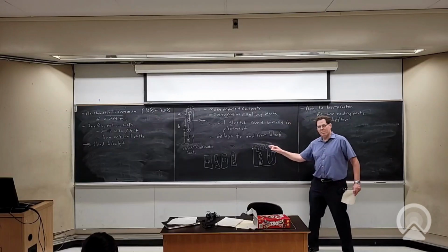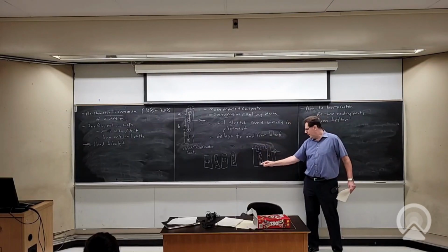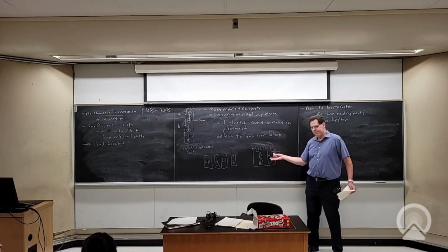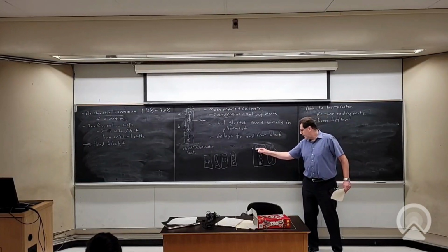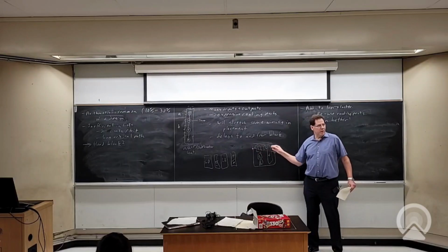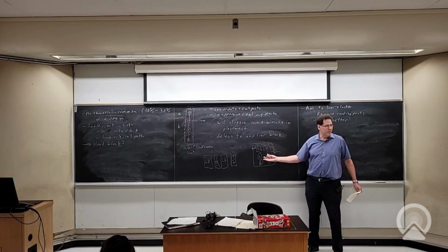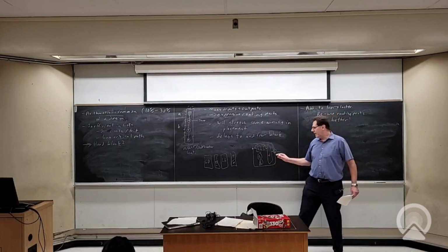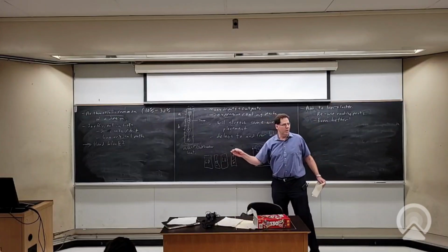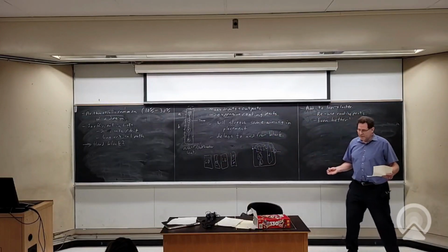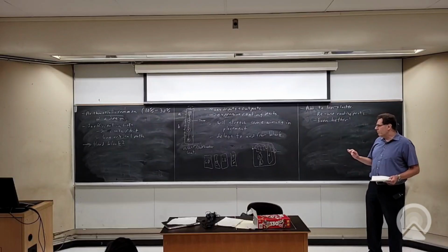And the outputs could go here and have a mux, where you do one or the other. Okay, so that's what I mean by reusing the routing ports. You build all the LUTs, you build the adder, this 16-bit adder, and you hook it up. The inputs go to 2 spots, and the outputs are muxed. And this will now not add that much area to the logic block, and I'll have one everywhere I have a logic block, so my placement engine will be happy. But I can do a bit better than this.